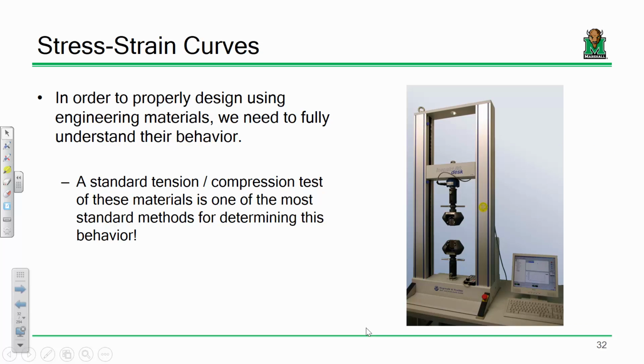At the end of class last time, I showed you all a video involving a tension test. The tension test is by and large the most fundamental materials test that we do in engineering, period. The long and short of it is we take a specimen of a given material of a standard size, and there are a number of different sizes that you could use. Depending upon whether you are civil or mechanical engineers, at some point you'll do a tension test in one of your courses. You won't do it in here, but you will do it at some point. If you're in mechanical, you'll do it in Engineering 215. If you're a civil, you'll do it in CE 321.